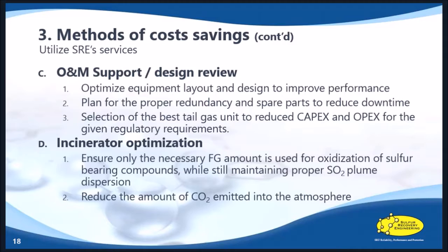O&M support design review. SRE, with our years of experience, we can make sure that the equipment is laid out ahead of time. We have one client that, they're telling me they had to hire in 2 cranes for their shutdown because they had to remove a condenser. But above the condenser was the converters, and above the converters was the reheaters. So in order to fix one condenser, they had to move 2 other pieces of perfectly good equipment. That's one design thought that wasn't considered during the equipment layout. Could have saved them a lot of money downstream. So really, operations and maintenance, conducting the work ahead of time is beneficial and saves you costs down the road.